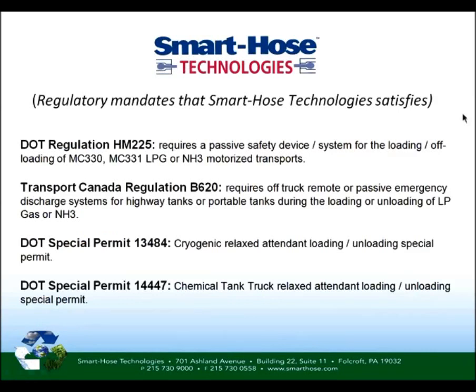There are mandates for LPG and NH3. DOT HM 225: if you are unloading a large over-the-road transport and you have LPG or NH3, you have to have a passive safety device. Canada Regulation B620 mirrors HM 225. Obviously, it just applies to Canada. And there are two DOT special permits: one applies to cryogenic and the other is for chemicals.